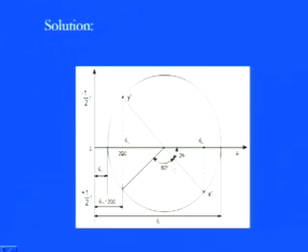Once you have the circle, now you see at this extreme corner of the circle will give you the epsilon 2, and this extreme corner will give you the epsilon 1. So, just measure those terms and you have the principal strains. So, this is the required first answer, that what will be the principal strains. Then once you get those things, simply measure this angle, because that will tell what plane it is.